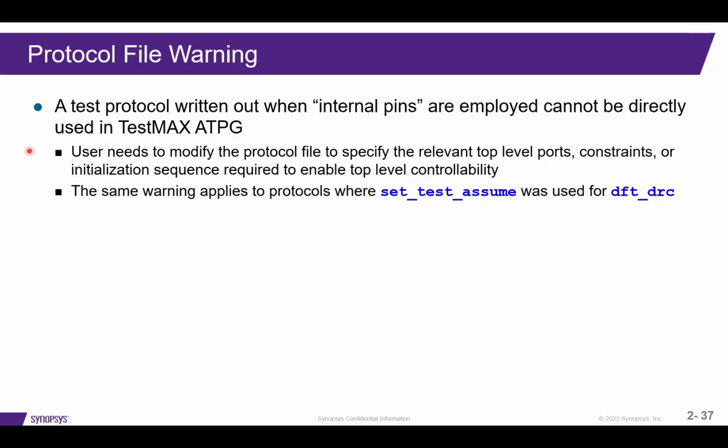A word of warning: the test protocol file written out with the internal pins flow enabled cannot be directly used in TestMax ATPG. You will have to modify the test protocol file to specify the relevant top-level ports, constraints, or initialization sequences that are required to enable top-level controllability.